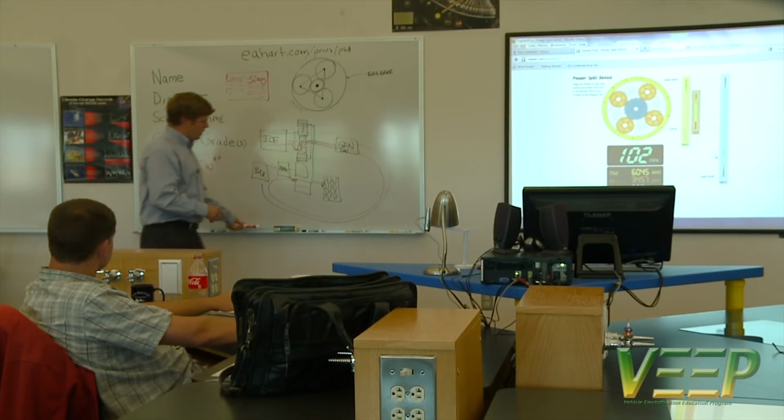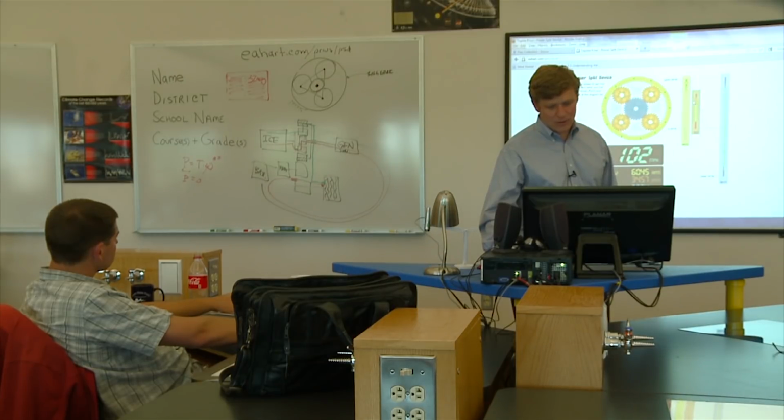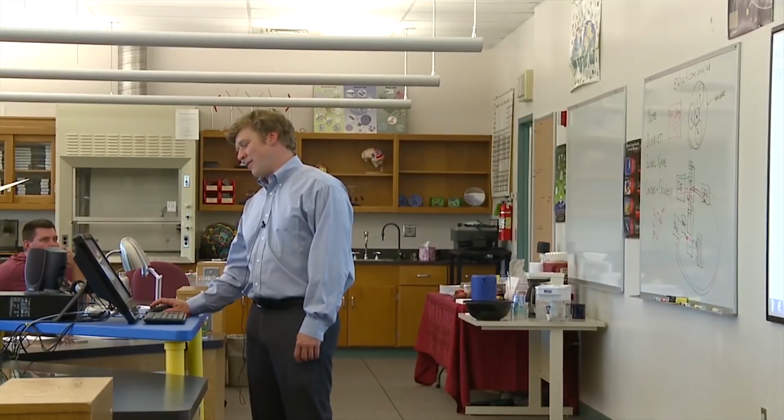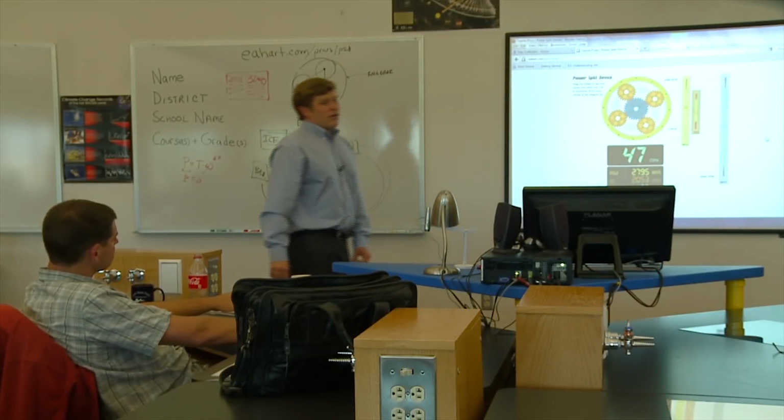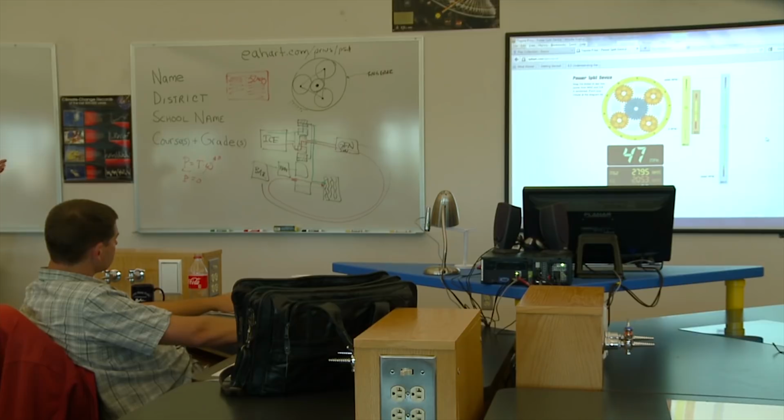So let's set the generator speed to 0 and watch what a parallel path might look like in the Prius. I'll set the engine speed to a reasonable speed, and in that case, you can drive 50 miles an hour down the road in a Toyota Prius with an entirely parallel power path.